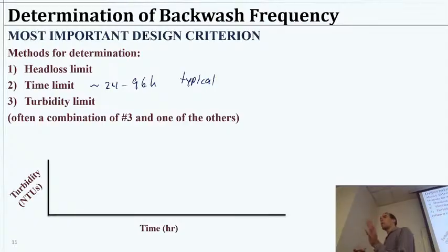So when we talk about this whole backwashing thing, I'm going to draw a couple diagrams here. What I really want you to pay attention to is what the total cycle looks like. We're going to ripen first, then we're going to produce water, then we're going to stop, and then we're going to do some maintenance and backwash. Then we're going to start again, and we're going to start with ripening. So it's that life cycle or that filtration cycle. We need to capture all of that to understand where the water is going in order to design a system that can adequately treat water.